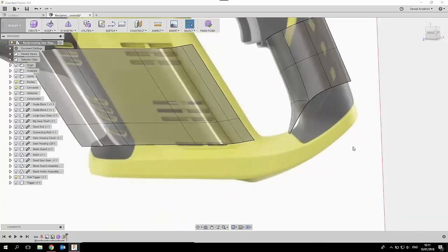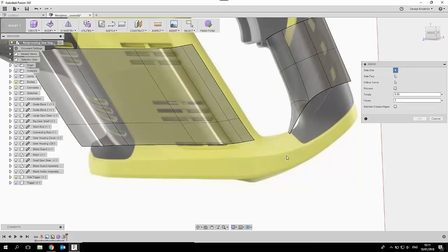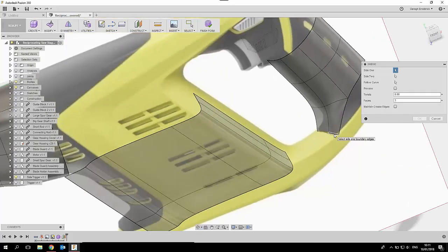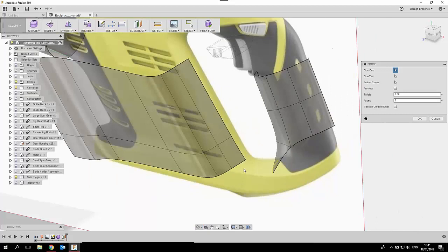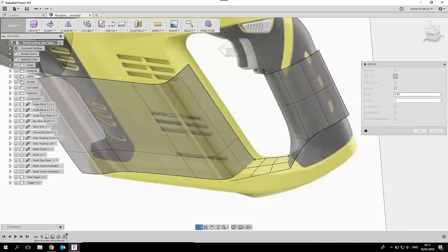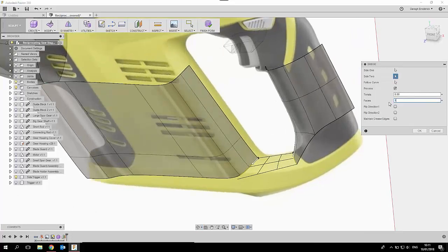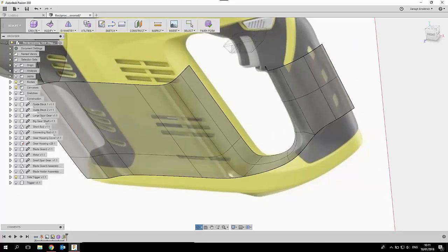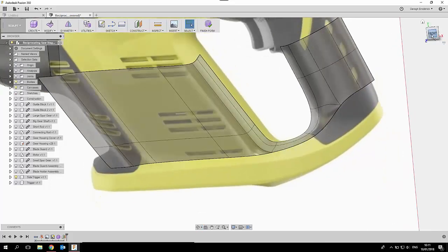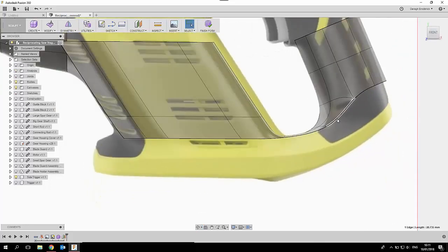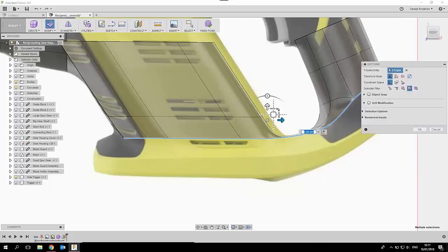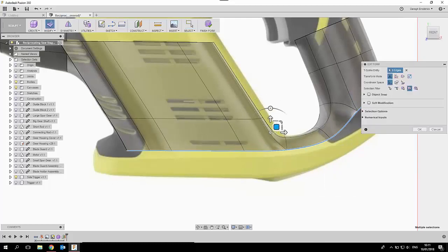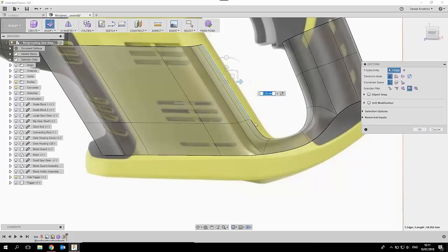And hopefully this time we can use the bridge tool again and we won't crash. Okay, so I can bring up a preview of what my bridge will look like. I'm just going to reduce that down to one face, and we've created our bridge. So I can double click here to select an edge loop, and I can simply drag that down. I can drag these edges in,